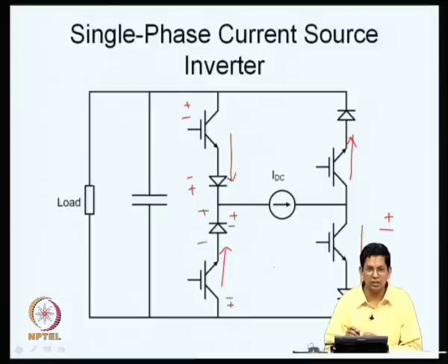As I mentioned earlier, a thyristor is a natural option to do this, but we can also use a transistor in series with a diode, the so-called anti-series connection. Why anti-series? As I mentioned before, you may have something which can block in one potential and another element which blocks in the opposite potential. So, let us say we take this transistor. This transistor is capable of blocking with this potential, whereas the diode is capable of blocking with an opposite polarity, while both of them conduct in the same direction. So, you call it an anti-series connection, and you get this done now.